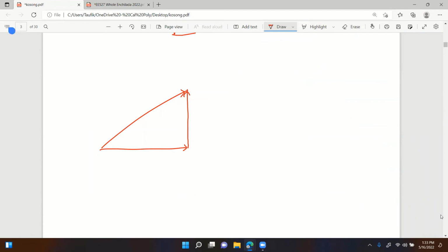just use the example we have in our house, for example. Let's say one of our loads in the house is drawing P and Q. Then the apparent power will be the hypotenuse, call it S1, and S1 is equal to V1 RMS times I1 RMS. And let's call this Q1, so we have P1, Q1, and S1.